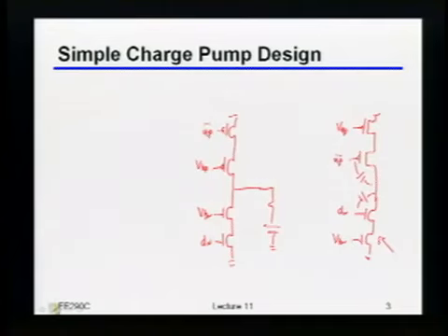And maybe I'll be, let's say, more clear. Let's say my loop filter is like this. If my loop filter is like that, what is my control voltage referenced to? Yeah, it's referenced to ground, right?